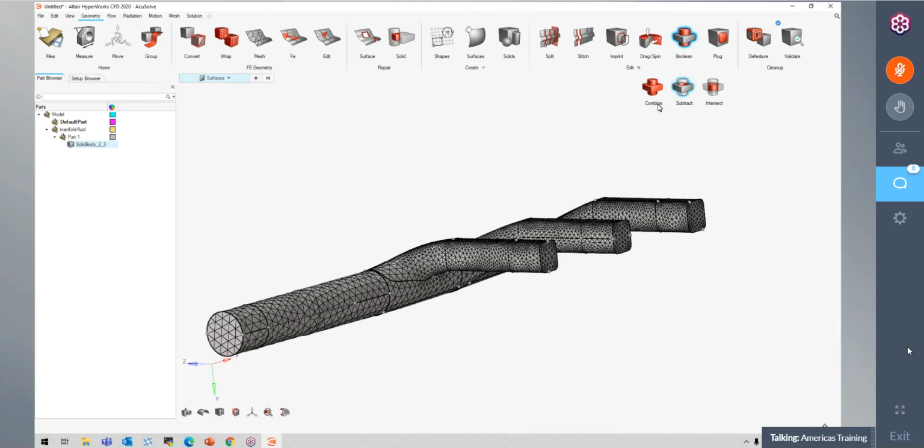So the Boolean operations would probably be the best way, but you do have these mesh fix operations. So you have these options to edit and combine and edit the mesh itself. These tools are normally meant for when you bring in a model that has a mesh already, or it's just a mesh and you don't bring in any geometry. That's when you usually use these, but you can still use them on this model as well. So depending on your setup, those are the tools that I would look at in order to try to connect things that might be separate without breaking the whole thing.